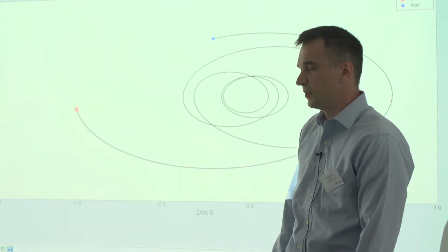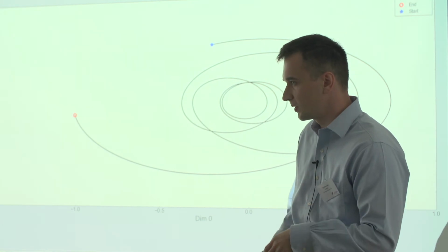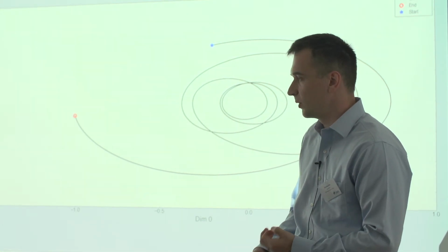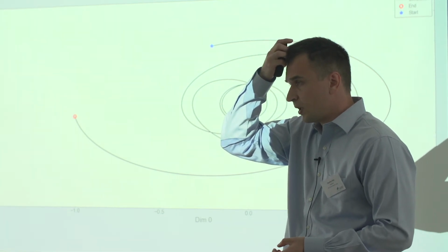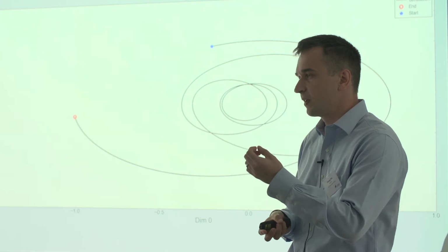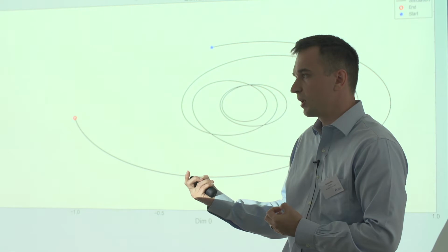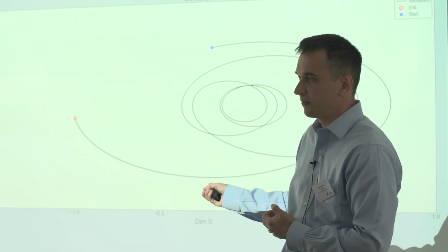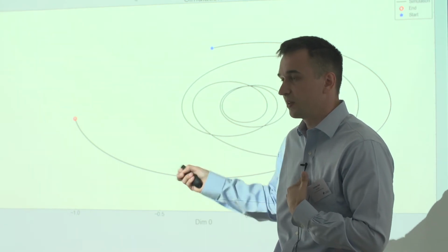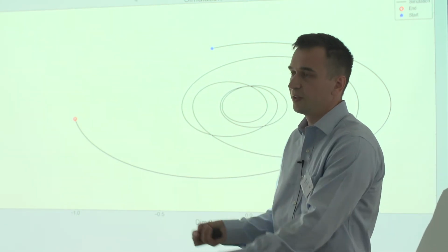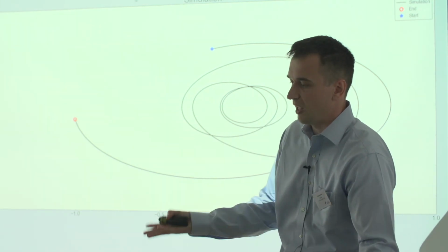To gauge the accuracy, because I think there were some questions before of am I using floating point or intervals, I'm using floating point here, right? So that's how you can get more speed out of it, but you also don't want to lose accuracy. So one gauge for accuracy you can use is when you solve the linear program, you have values of your start state and your predicted final state, right? So what you can do is run a high accuracy simulation after the fact and compare what the high accuracy simulation says the final state is, and what HighLow said the final state was supposed to be, and look at the difference between these 2 states and gauge if it's accurate enough.